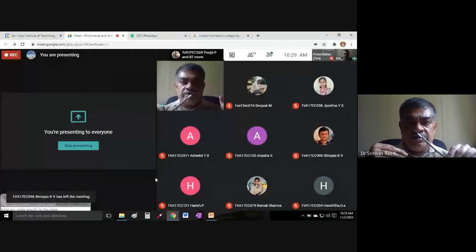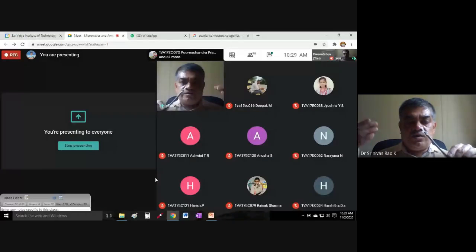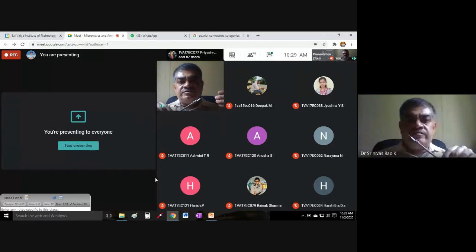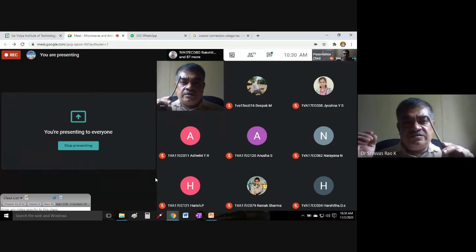Now, the moment I increase the power in terms of kilowatts, your transmitter is producing power in kilowatts instead of watts. In the reflex klystron, we found that the power handling capacity is very, very low. It's a low power device. So it was generally used to generate power of approximately somewhere around milliwatts, or could be watts, something like that. At that time, I cannot use the waveguides. I have to go for the coaxial cable for efficient signal transmission.